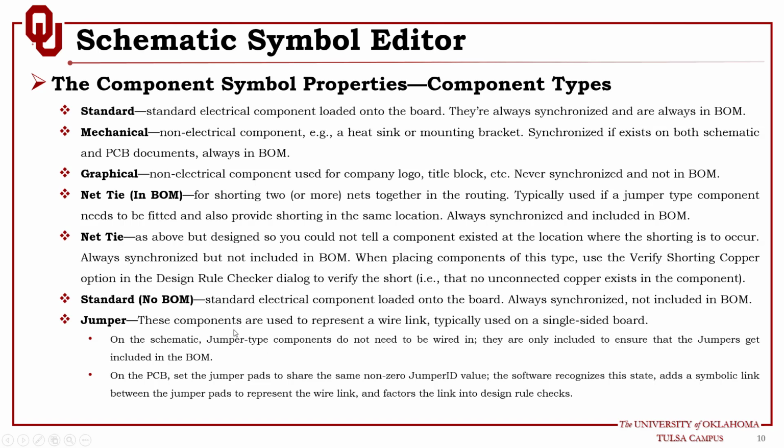Now, in what situation will you have a component in your design that is not placed? In so many situations. If you hold any printed circuit board and look into it, you will see places for components that are not populated or not assembled onto the board. Why is that? Because sometimes you have to design a board to work in different products in different configurations, and also to account for different functions.